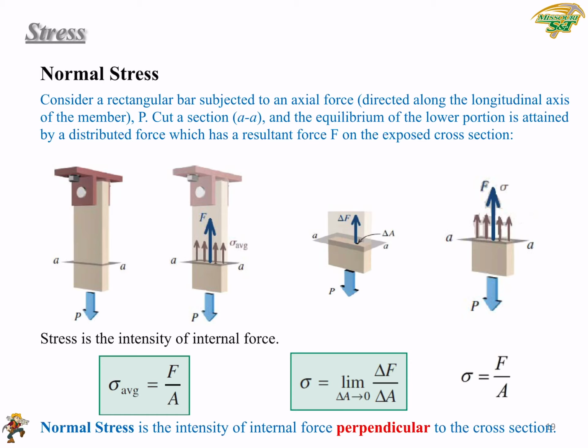So we have just defined stress, and we have known that stress is the intensity of internal forces. So based on this definition, we can calculate the values of stresses. It would just equal internal force over area. But to correctly calculate the values of stress, first of all, we need to identify the type of stress we're calculating. Then we need to find the correct area we're using in the equations.